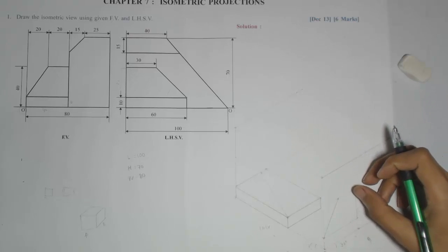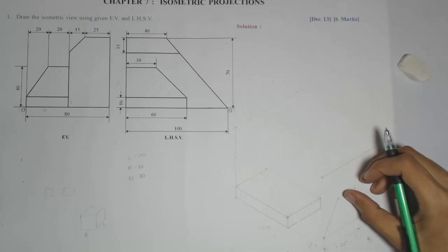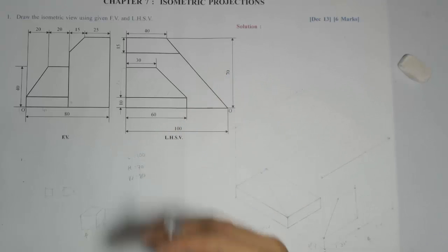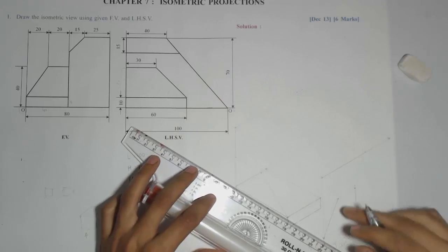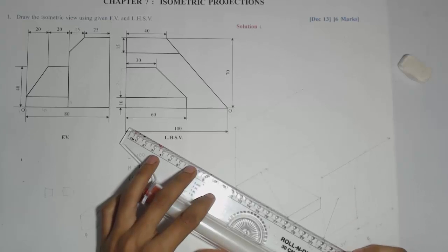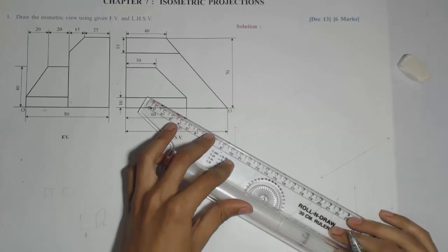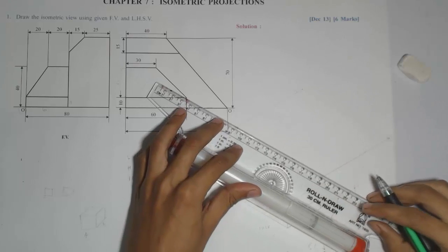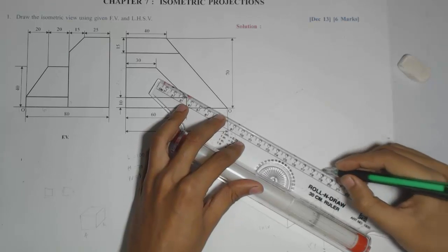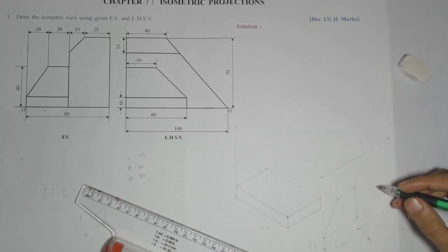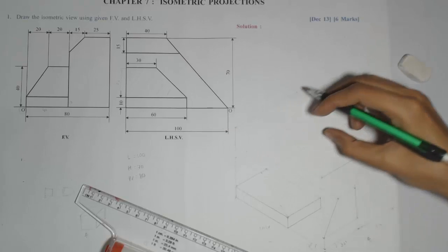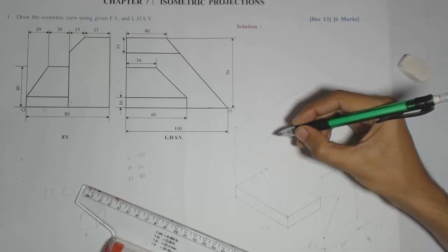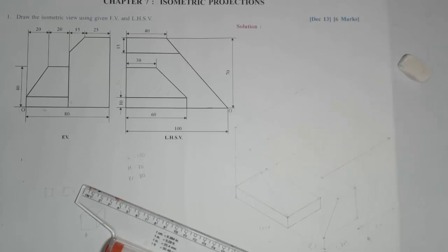But these 2 corners along the width I need to produce up to the entire length, because it is again starting from the opposite boundary of the rectangle. So for these 2 corners I'll go up to the entire length, maximum up to this projector. Now if you see the intersecting points for both the projectors from here and here, I'll get these 4 intersecting points, right?